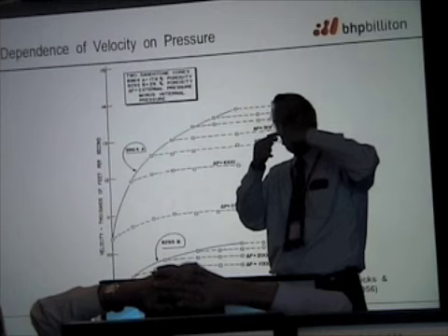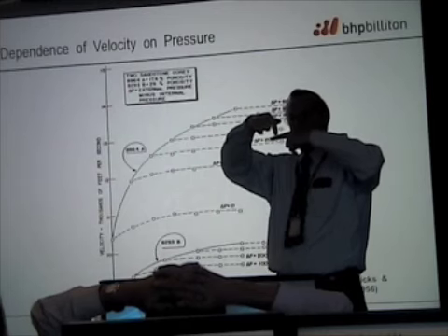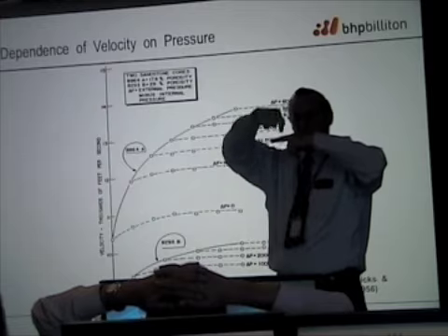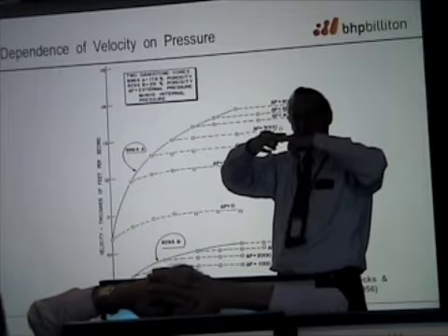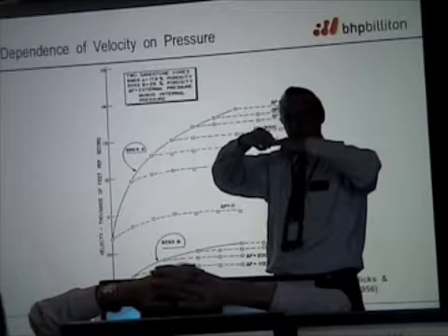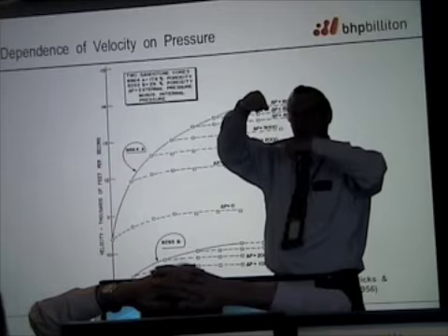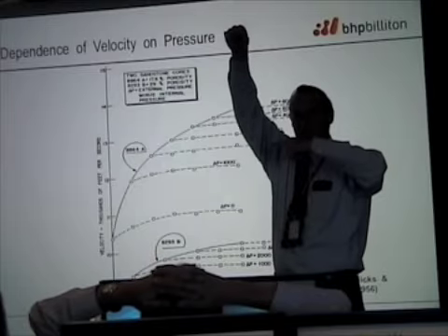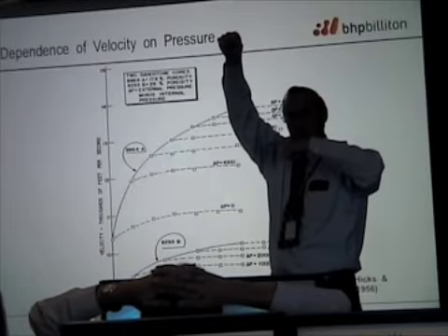You have to have whatever kind of transducers you're going to use. Running through the head is a stainless steel tube which you weld onto the end piece, and the stainless steel tube comes out of the pressure cell, out the top of the pressure cell. You've got to have a good pressure seal there, but that's doable.